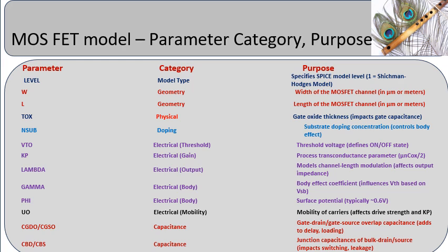Device's physical structure, geometry, electrical properties, parasitic elements etc. influence the device parameters and are included in the device modeling. Some of the parameters' impact is explained below. Physical dimensions like W and L of the device will impact the device current capability. The gate oxide thickness influences the gate capacitance and thereby the device current capability and threshold voltage. Substrate doping influences the body effect.